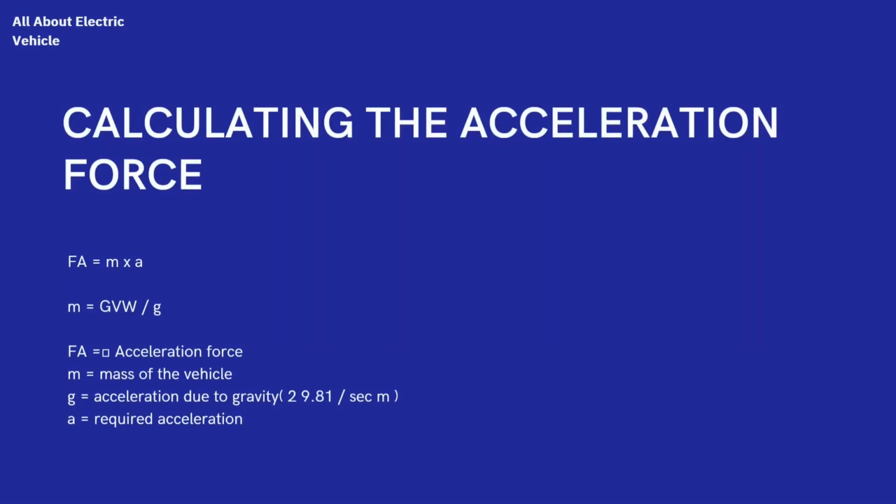Calculating the acceleration force. Acceleration force is a force that helps the vehicle to reach a predefined speed from rest in the specified period of time. The motor torque bears a direct relationship with the acceleration force, isn't it? Right. Better the torque, lesser the time required by the vehicle to reach a given speed.